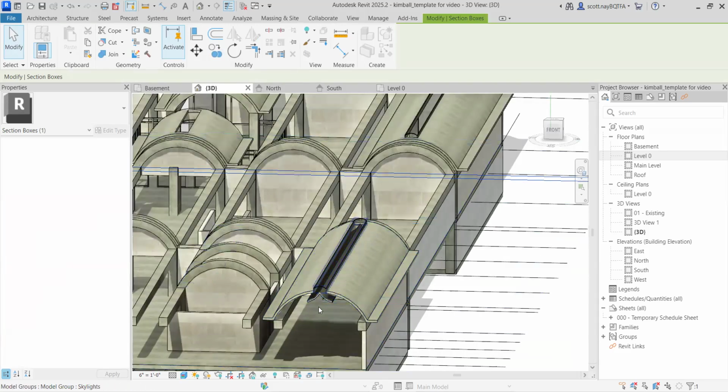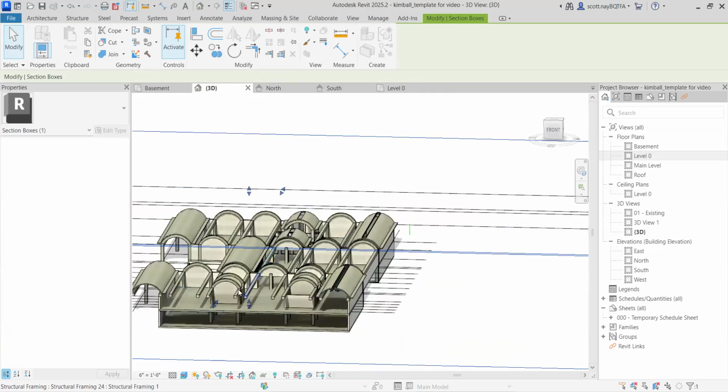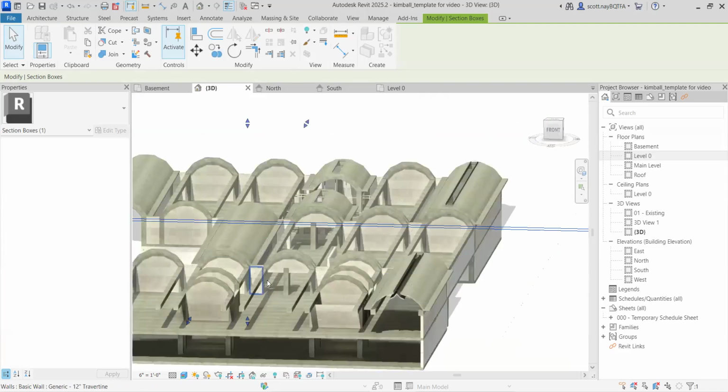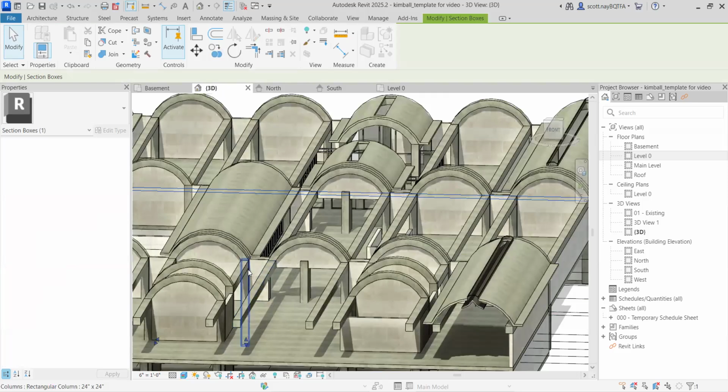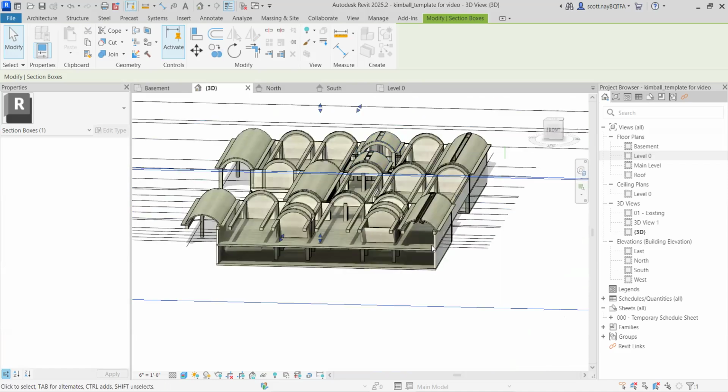So with the skylights and this diffraction, when you get to the courtyards, you just have to treat them like you did the carrying beams. So you have to shorten them so that they're not cutting through the courtyard, and then copy them over and make them the correct distance for the other side. And that is it for the roofs, skylights, and light diffusion.